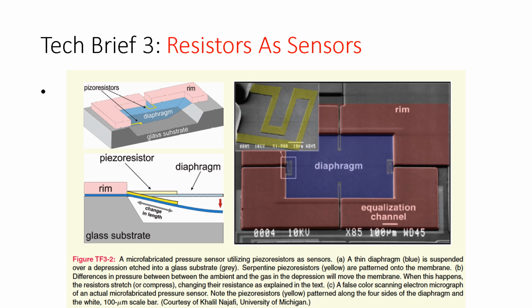There's also piezo sensors in biomedical engineering whenever you're trying to do like orthotics or any studies about the foot or how the foot is landing. Because if you put piezos down and you have somebody step on them, you can get a very accurate description of where the distribution of their weight is on the pad. And there's some other cool things you can do with these as well.